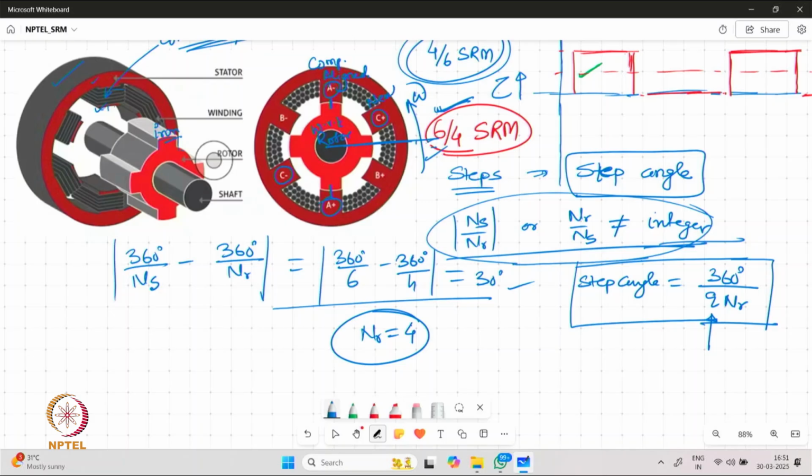So we can mark this as next aligned. Whereas the third set of coils, or the last two poles, as the rotor is moving away from this, is moving towards the most unaligned position.